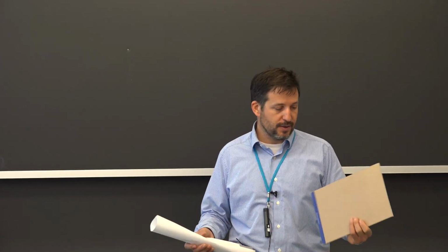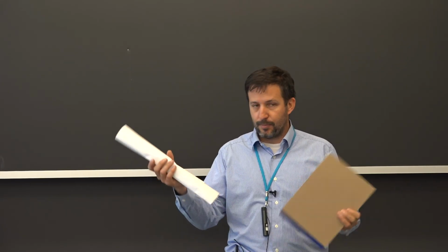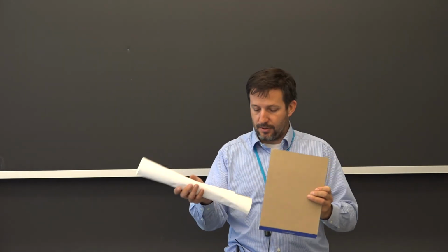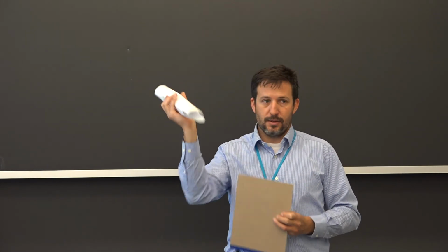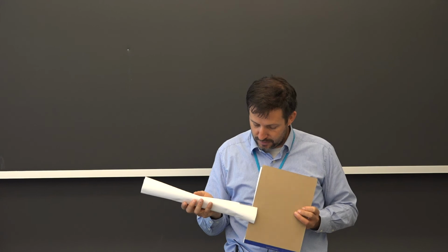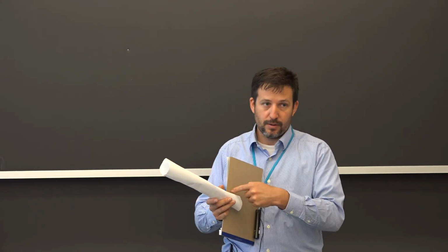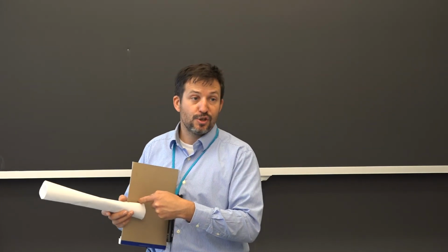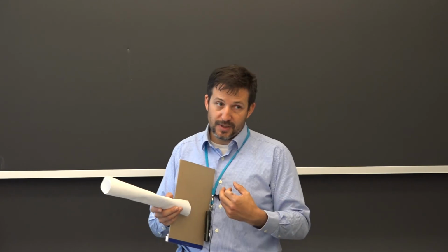So the variation of this is a bunch of gusset plates that you assemble together, and then you get your tube, you make a slot in the tube, and you assemble it, and then weld it on each side. You don't weld the end here because that creates a weld that's in tension, and that's loaded in shear. So you avoided some of the detrimental effect of making the weld by creating more area for the load to transfer into that joint. It's just so important.